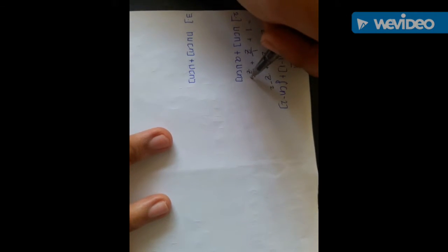We already know the identity of this f of n is equal to 1 at z equals 0, since the delay is equal to 0, as we see. Yes, we have a delay equal to 1, so it's the inverse of z. Yes, a delay of negative 2. For more simplification, we will have a value of 1 plus 1 over z plus 1 over z squared.